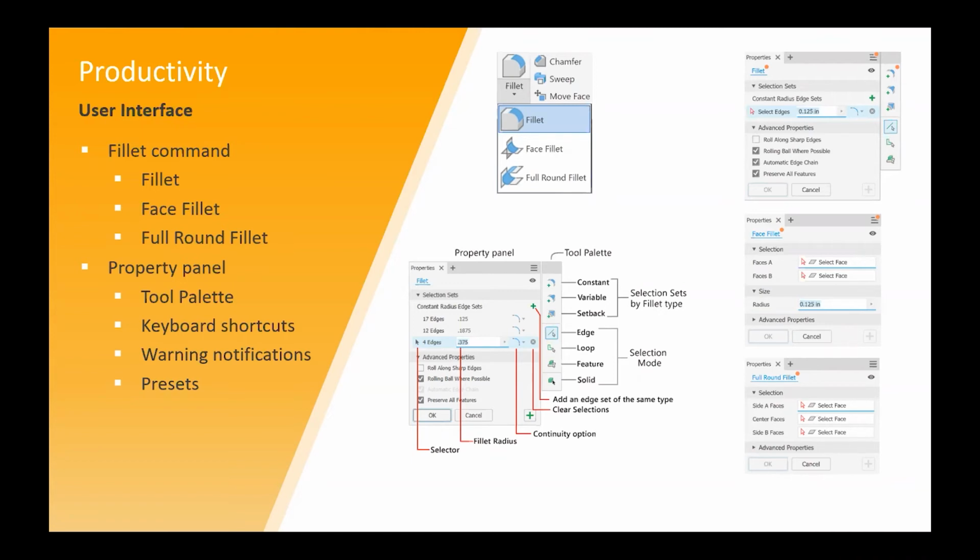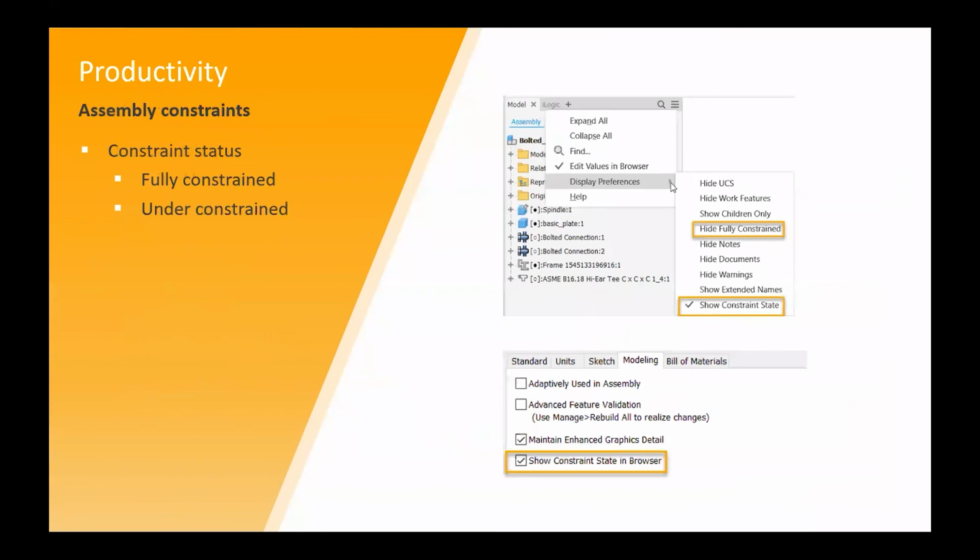So with regard to legacy files, if you're opening a previous version of an Inventor file, the fillet features will not change until you edit the fillet feature. Thus, the fillet browser nodes appear as they have in the past until the fillet is edited. So if you make an edit to a current fillet, it will be migrated across in the browser at that point.